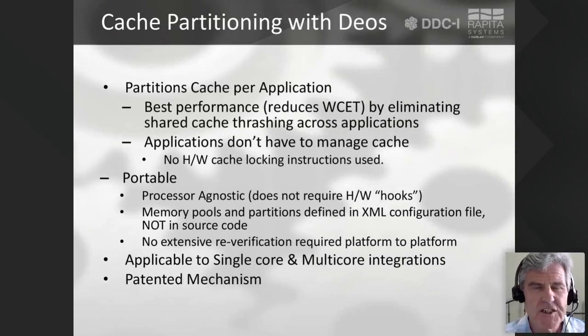So, setting up a relationship to achieve the cache partitioning addresses the CAST-32A concerns regarding the cache and memory interference patterns. The integration feature minimizes the cache and memory bus controller interference, and the defining factors are going to be the size of your memory, the size of your cache, and the availability of cache on the hardware. Basic idea: based on cache memory designs of modern processors, regions of memory pools are associated with particular cache lines. The integration then allows you to assign those memory pools, which are associated with particular cache lines, to specific application partitions. Other key points here: this feature is patented.